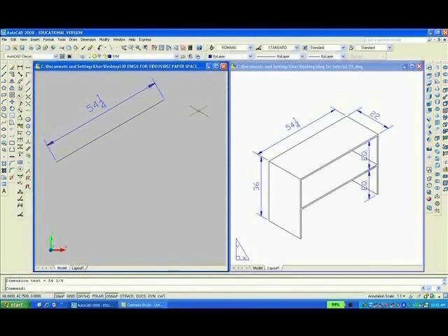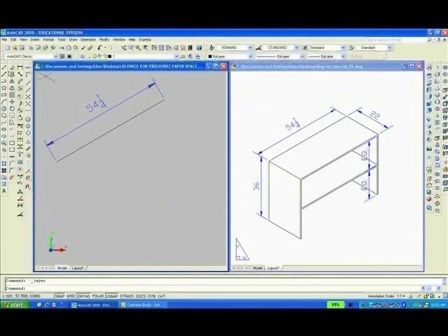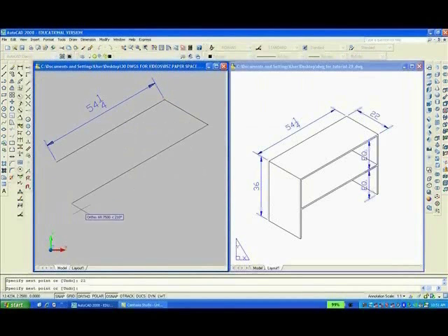So we'll continue drawing the figure. The next thing I'll do is, of course, go back to layer 1 being current, and then I can draw the line from the endpoint here, 22, enter, 54-1/4. You can also use decimal equivalents like the 0.25, and then connect it up there. So that, you might say, is the top view.